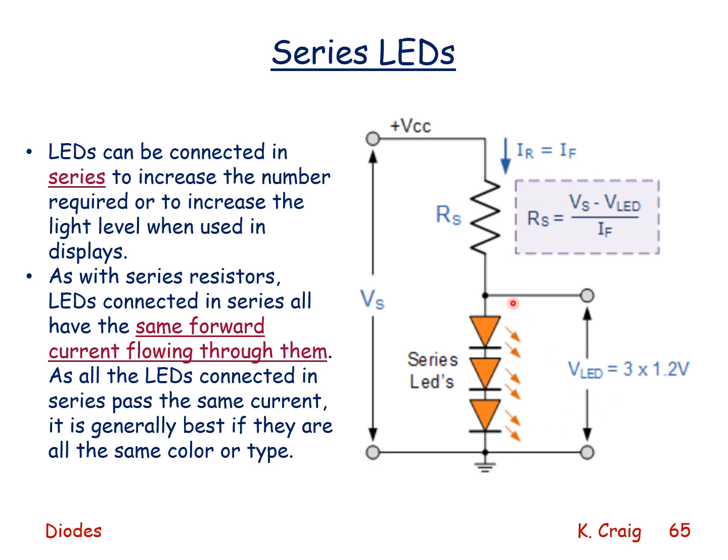The voltage drop across all of the LEDs is 3 times the voltage drop across one of the LEDs. And we size the resistor using our same formula, supply voltage minus the voltage drop across the LEDs, divided by the desired current, and that will then size the current limiting resistor for us.